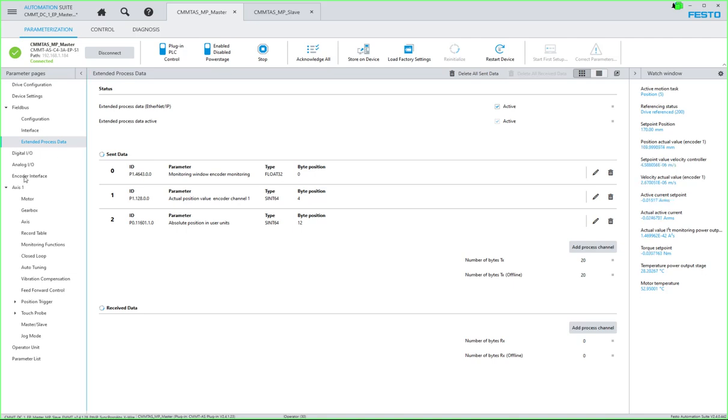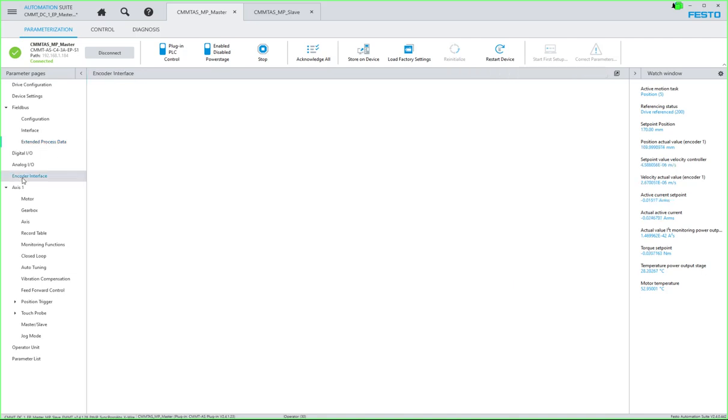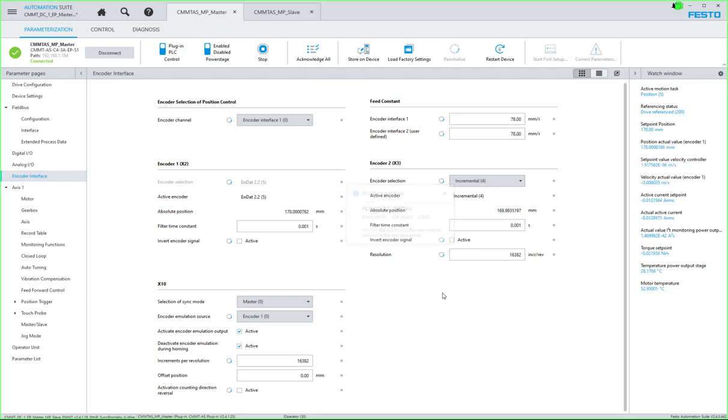So basically, if I'm out of sync and the gear in is not active anymore, the first thing I'm going to do is come through my master here and look at this position and compare it to this position. And if I'm not synchronized to each other, then I need to set a master position of this X3 port.